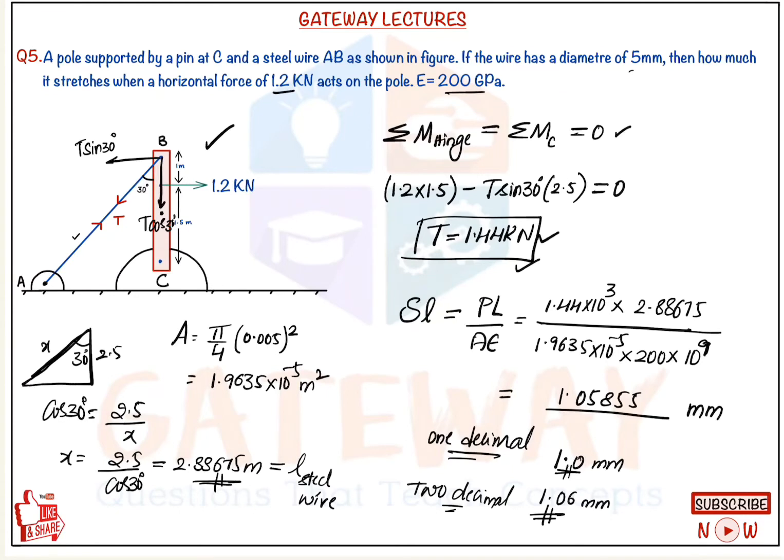If you find coplanar and concurrent forces, then we can use the triangle law, or Lami's theorem, etc. By seeing the question itself, we can get the idea to apply sigma Fx, sigma Fy, or moment about any point. Here it need not be a hinge point. Actually, if it is in equilibrium, it can be any point.